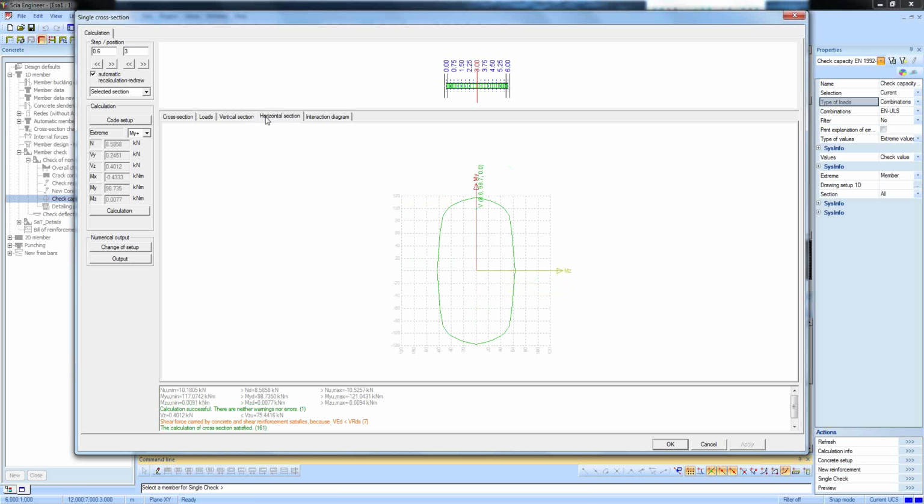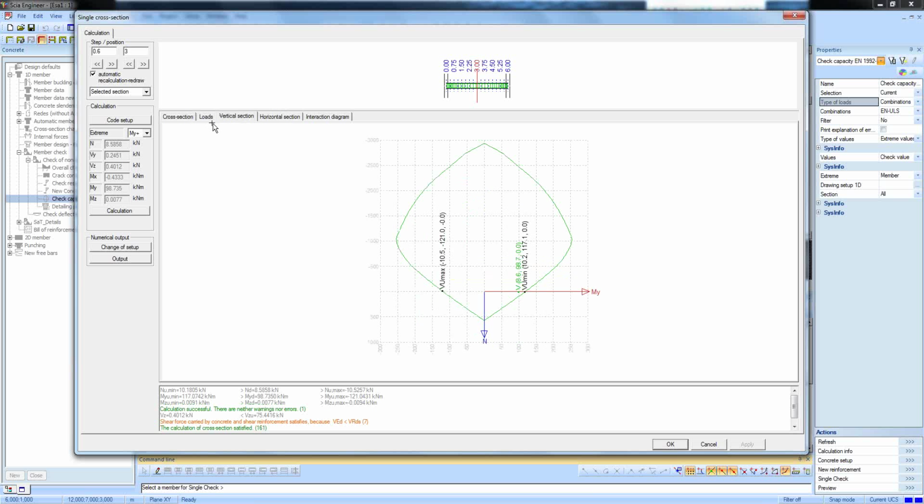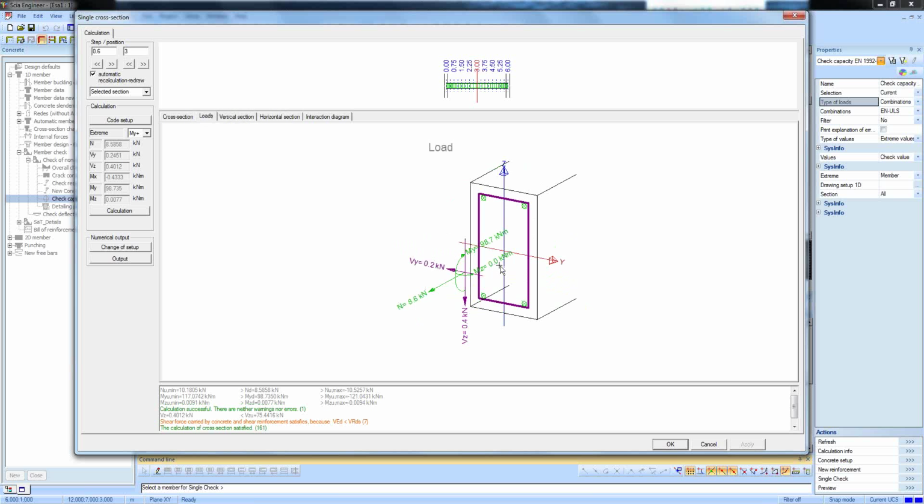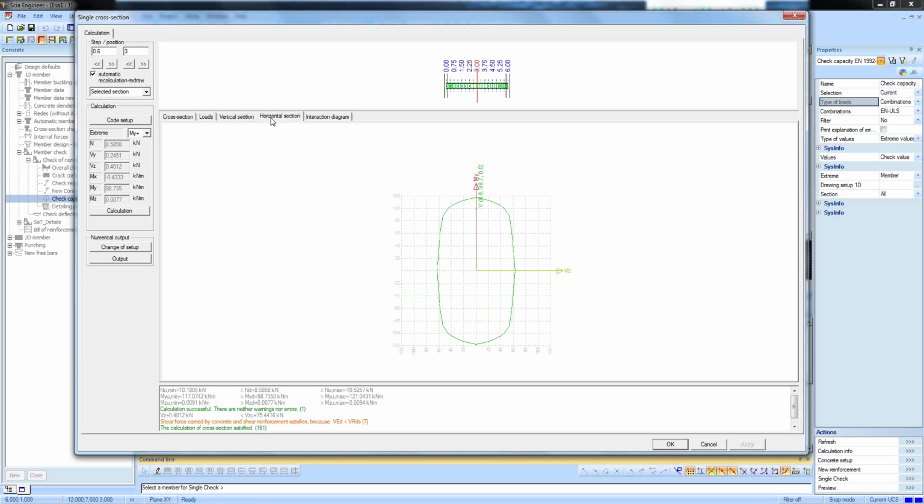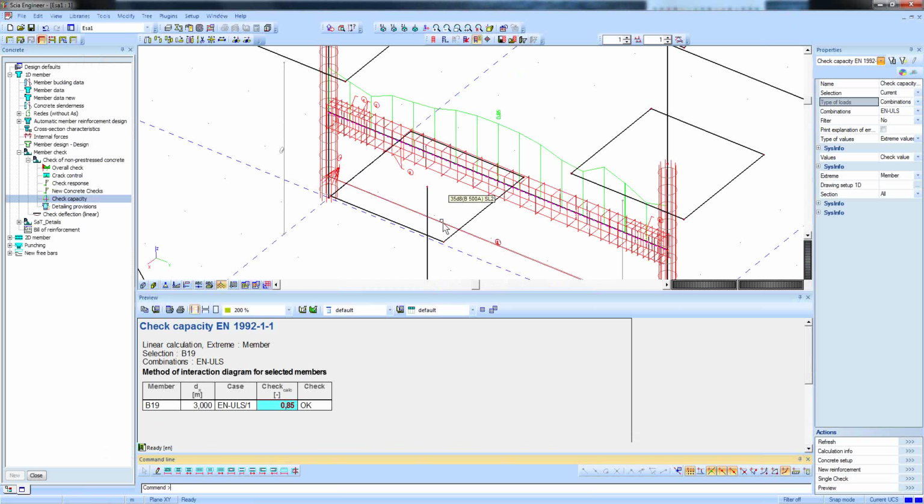But as long as I remain in these two sections, then that means that I can take on these forces. And these loads, which you have here, are inside these horizontal and vertical sections. Otherwise, I would have an error. And I would have to solve that error by augmenting the amount of reinforcement or something else, but making the reinforced section stronger. That would be the solution.